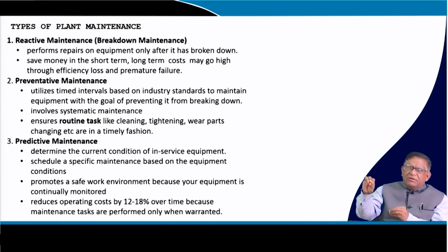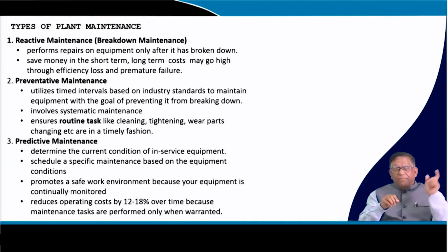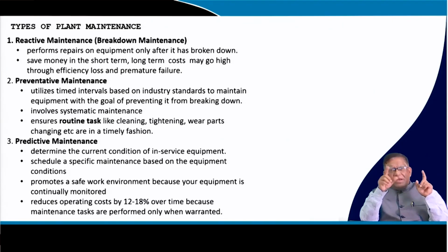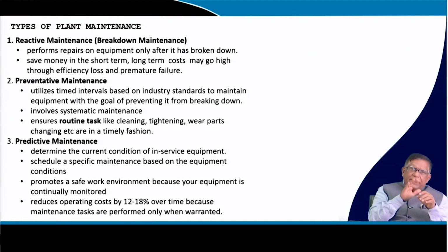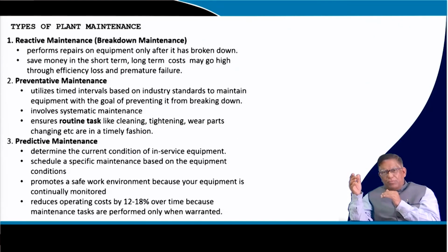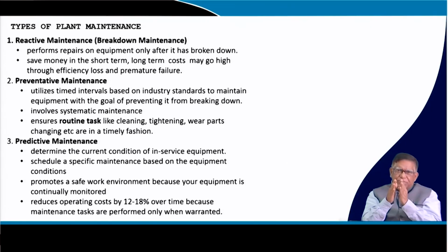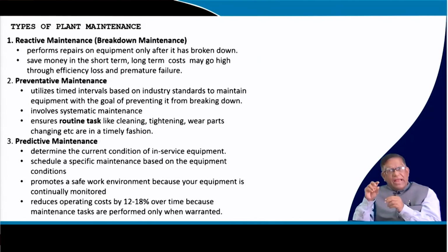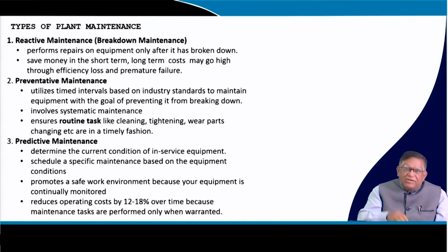You keep a sensor over there, and then you keep monitoring how the vibration is coming. Then they will find, okay, only this bolt, maybe by tomorrow or after tomorrow it may become more loose. So when they see a trend of getting loose, at that time you go and just tighten that one.